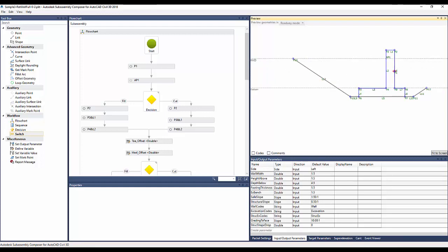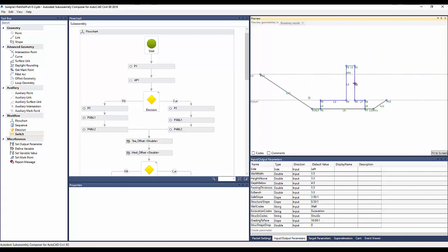We also have it so that the top of the wall is going to expand and contract with that. And if you notice, the toe and the heel actually get slightly bigger. This is a chart that we were given by our structural engineers that we ran a regression line off of to determine the relationship between the height and the toe. If you ever want to see a structural engineer twitch, tell them you ran a regression line on a loading chart that they gave you. But these aren't for final design. These are for really rapid earthwork calculations. So that's the purpose of this one. It actually gets used on our projects.